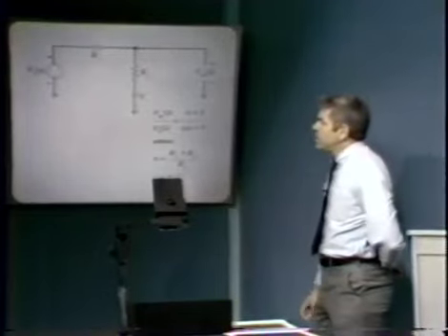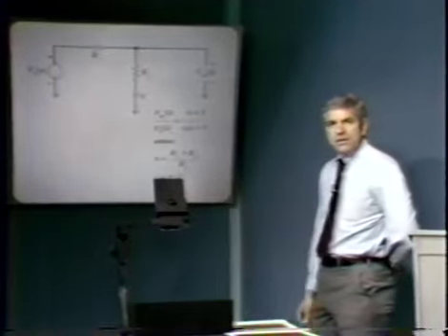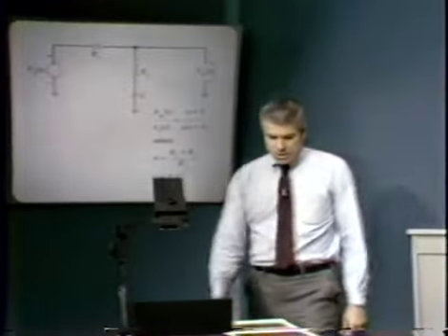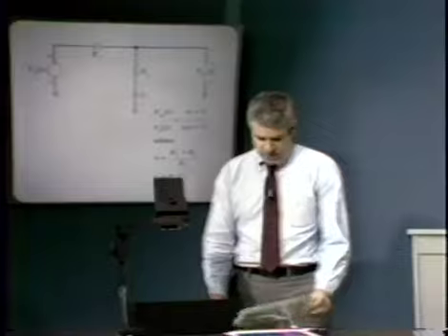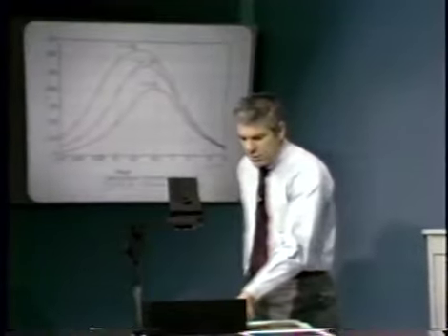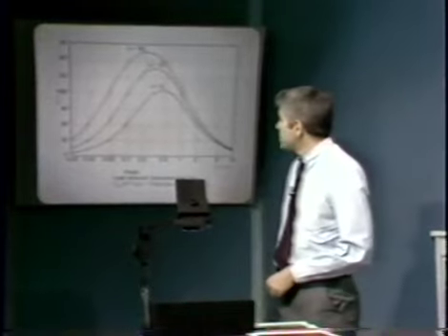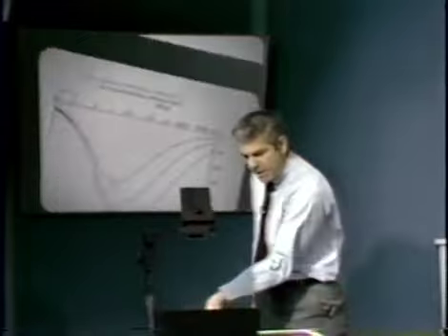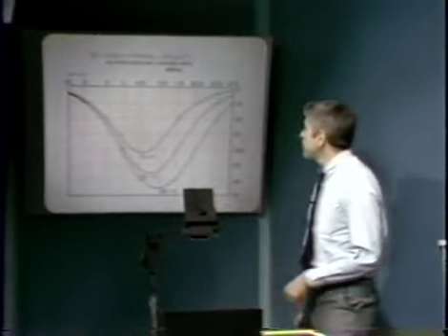As the name implies, a lag network gives us lagging or negative phase shift at all frequencies. And let's look at the phase shift characteristics of a lag network. For a lead network, we said that we have this sort of characteristic, positive phase shift at all frequencies. Well, a lag network basically gives us characteristics like that.